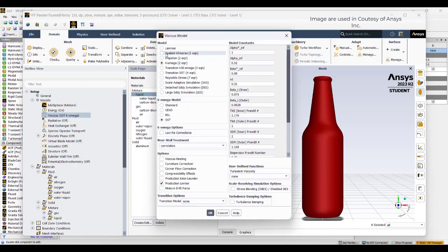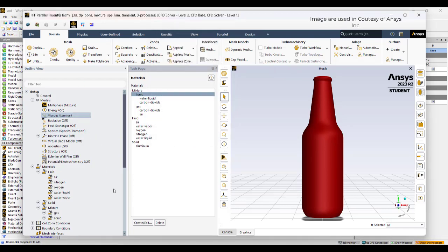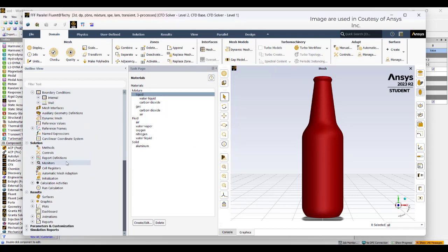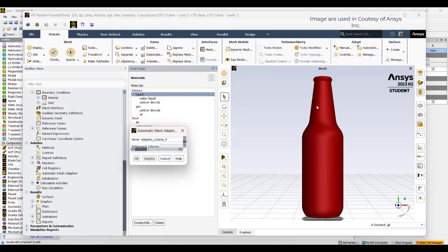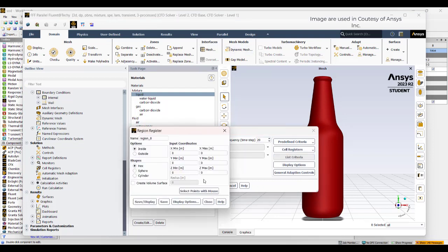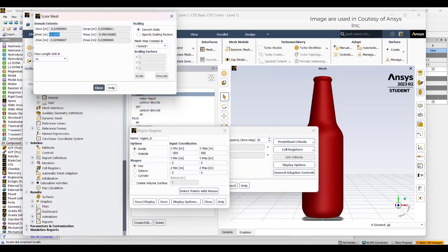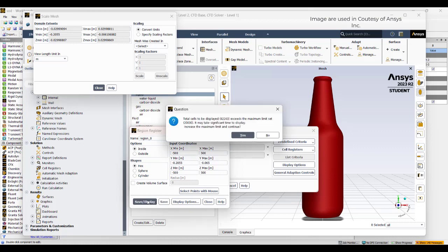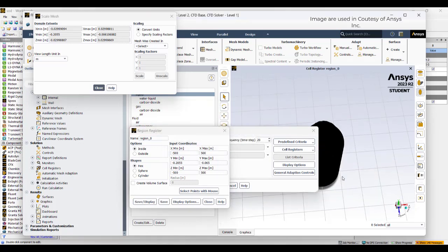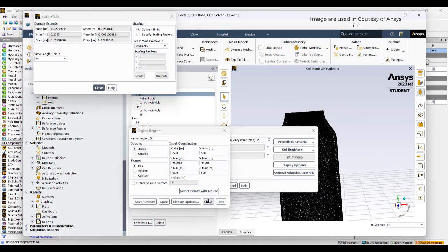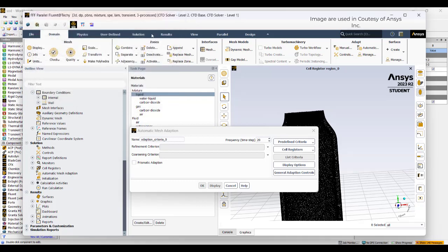Right now, go to viscous. I'll turn it into laminar because it's not necessary anyways. We'll not solve the flow equation at all. And now we need to create a region so that we can apply our pressures. Cell region, new region. I'll take some random values because if you go to scale, you can see the values are in Y, which you need to patch. So the minimum is, and I'll go up to minus 0.065, and Z again some random value such that it is out of the scaled values. Now save display. Yes, it is coming up to this refined portion. You can see it's coming up to refined portion such that our interface falls in that refined portion.